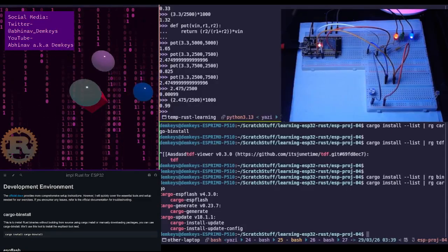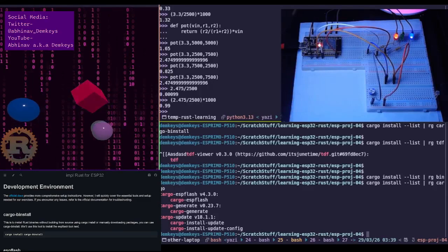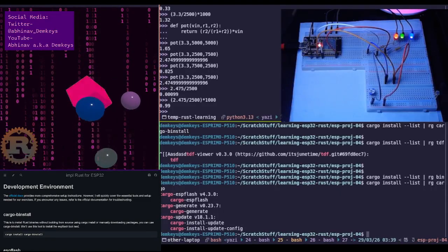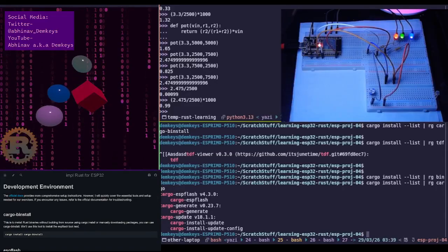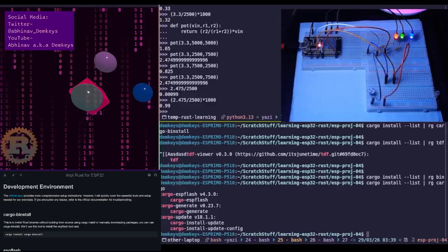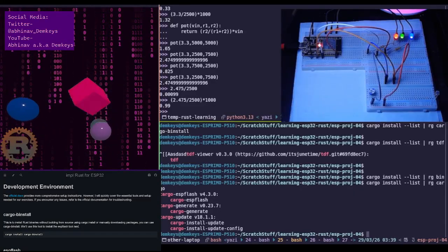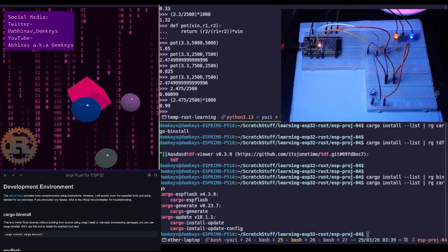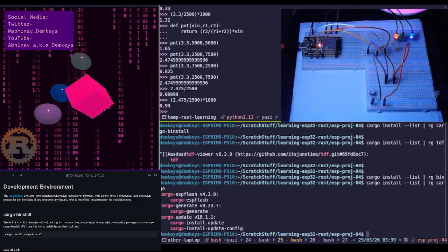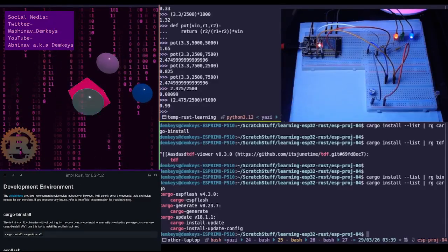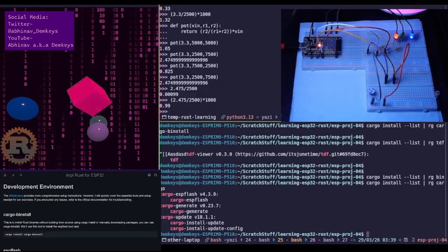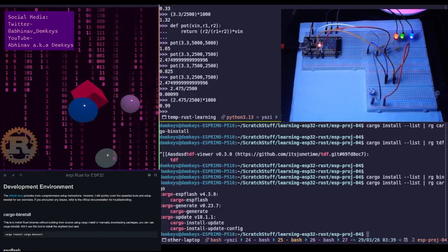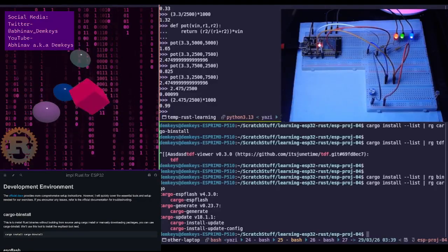And I'm kind of excited because I looked at some of the code examples. And fortunately, I think this is thanks to embedded HAL rather than thanks to the CH32 HAL itself. I think this is because of the embedded HAL, because embedded HAL has a standard set of traits that need to be implemented by whatever microcontroller HAL is being implemented, because that HAL is implementing embedded HAL.